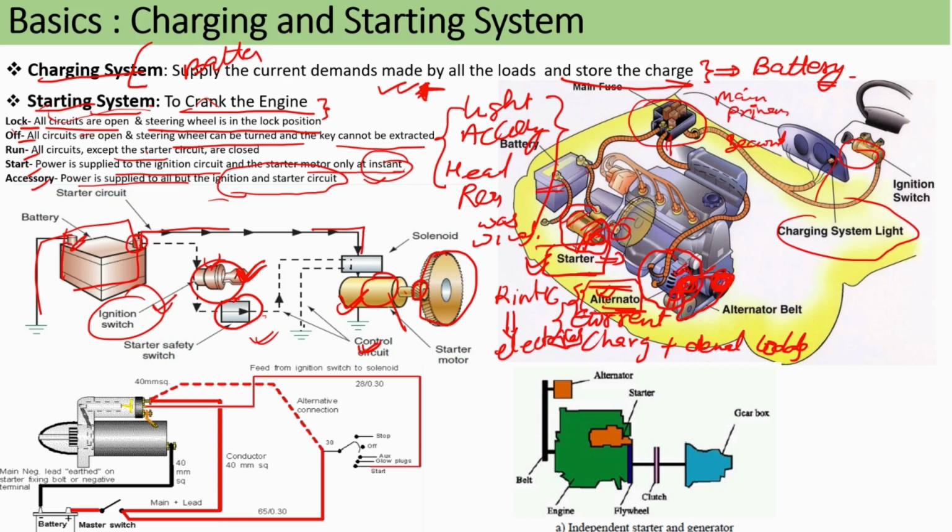One thing you might have seen is that the starter motor is used only to crank the engine. After cranking the engine, the pinion, which is engaged right now, will disengage. It will disengage because you cannot rotate with the flywheel of the engine, as the engine RPM is higher. You might have seen many times that if it is engaged in the running condition of the engine, then your starter motor is gone or damaged. So starter motor is used to crank the engine only. Then it becomes an idle part of the vehicle. Once the engine is started, there is no use after that.